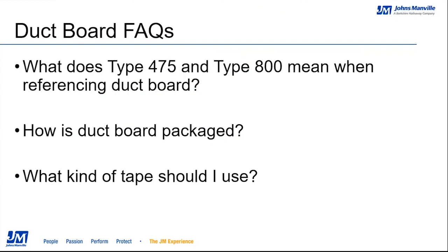When dealing with ductboard fabrication, you should always use an approved UL 181 A-P pressure sensitive tape to seal, seam, and join together ductboard. A strong permanent closure is absolutely essential for the proper performance and longevity of a fiberglass duct system. The use of an unapproved closure material, however, can result in a duct system failure that none of us want to participate in.